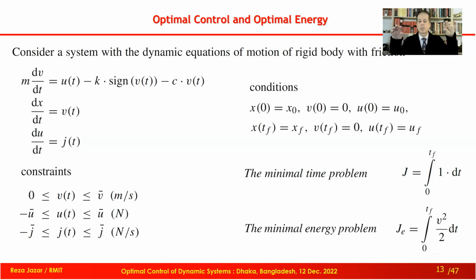So there is an end condition and a constraint on input or other kinematic characteristics. For example, we have a limited input. Limited means there is a saturation. There is an upper limit or lower limit for the input. And also, we wish to go from here to here. Maximum speed is something. Okay, so it means another constraint with maximum speed or maximum jerk or maximum acceleration can also be applied. So constraints can have a variety. The simplest one is a limit on the input.